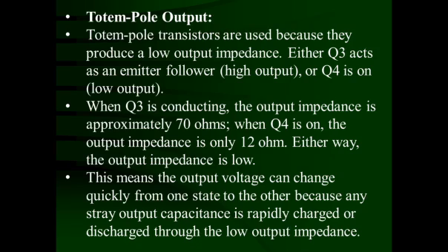You know that at the output of the amplifier, there is a distributed capacitance called load capacitance, CL, which is going to be charged through this output impedance, and charging of this capacitance takes place through an RC time constant. That means some factor, maybe 0.69 or something, multiplied by R into C. So if the value of this output impedance is very low, the charging time of the capacitor is very low. That means the RC time constant is going to be very low, and it is discharging very fast also, because the RC time constant is low.